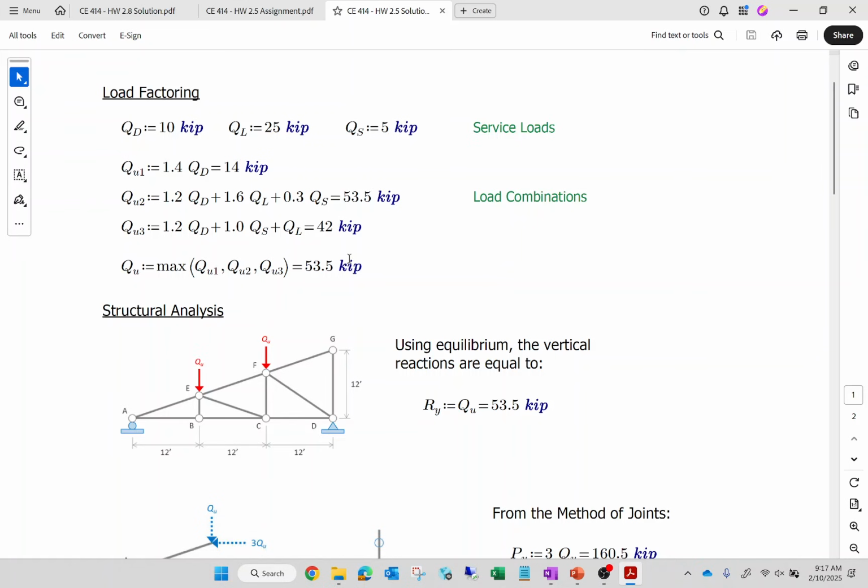So this vertical reaction right here, if this is Q, I've got 2Q down, I've got to have 2Q up, so the vertical reactions here are Q apiece. Is everybody okay with that? That good? So past that, all I did was a method of joints problem.